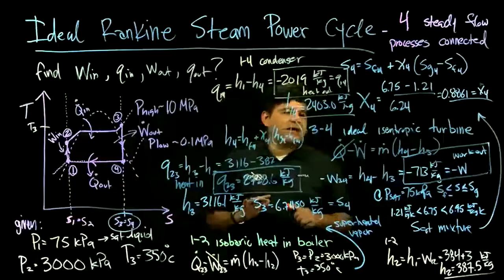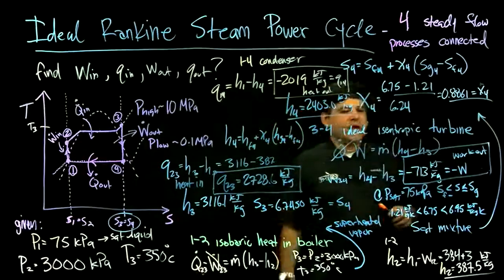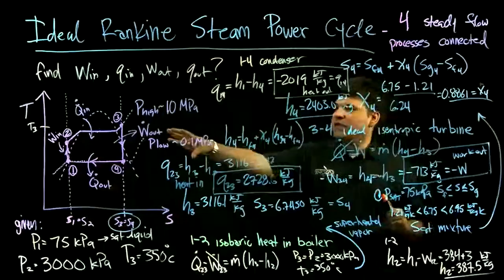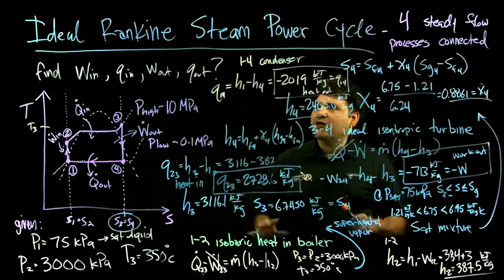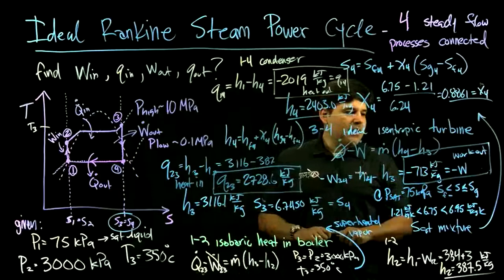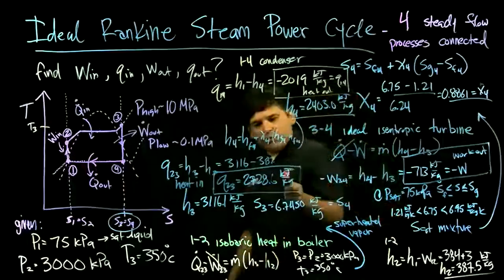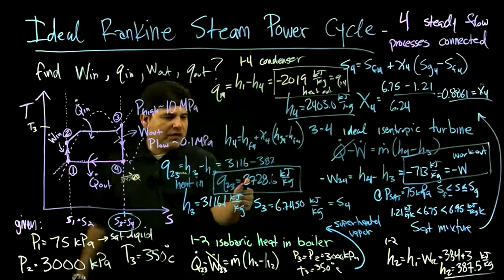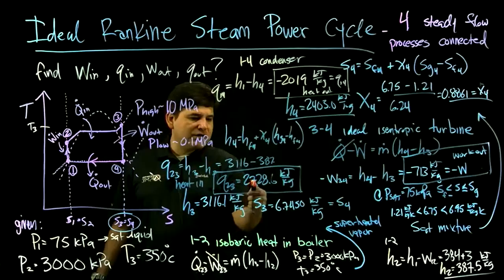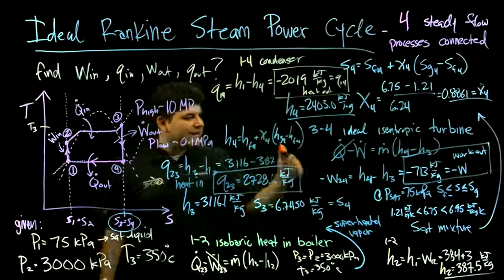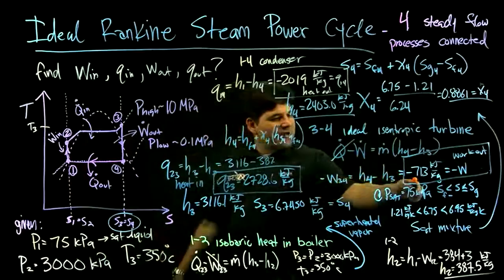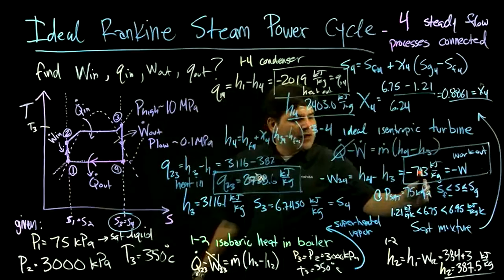Okay, where does that electricity go? What happens is, for these typical conditions, even with a lot of these assumptions, these are pretty typical values, you boil water with 2,700 kilojoules per kilogram of water, but you only get 700 or so mechanical work out.